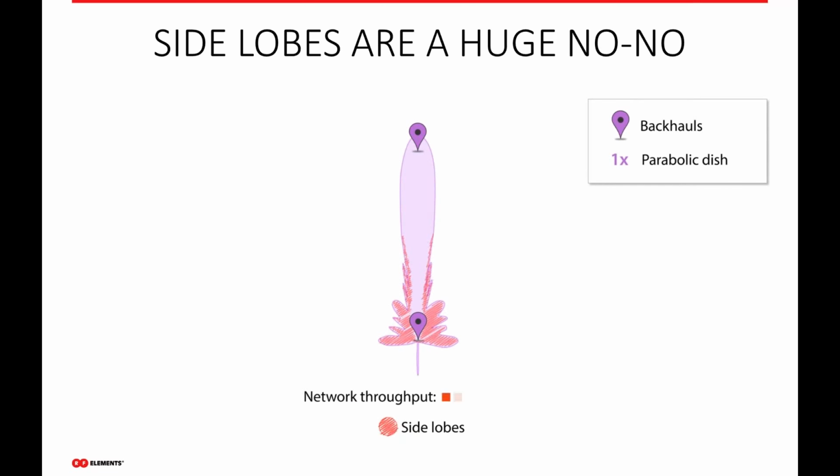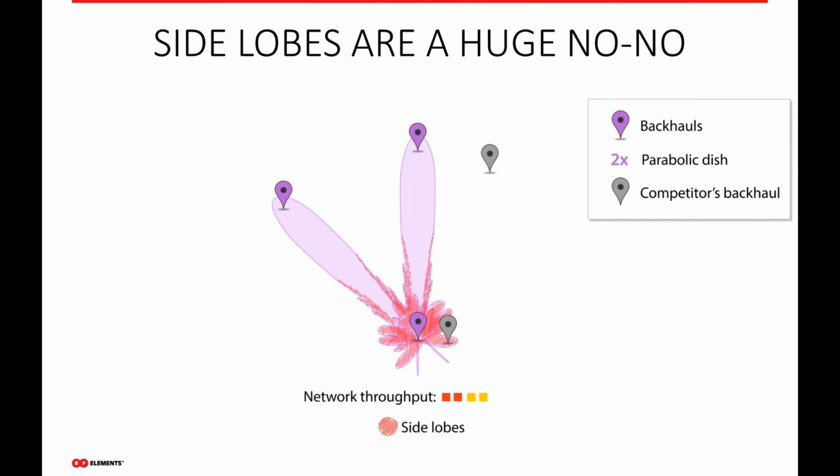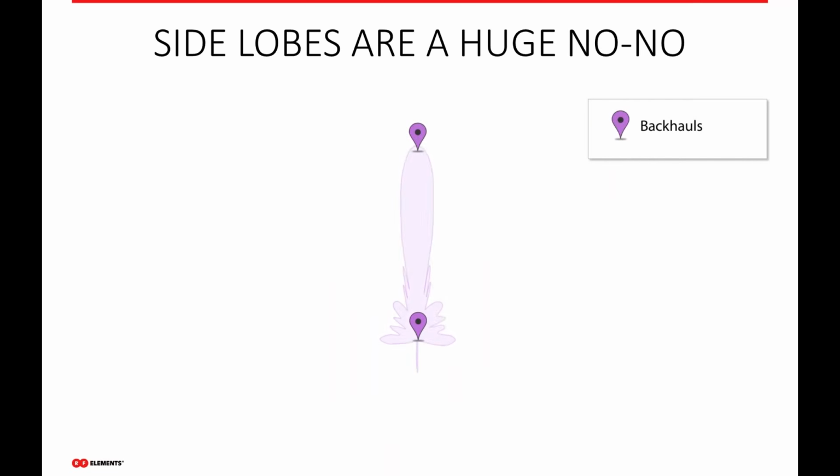Maybe it's on a guy leg where you have these big distances. Again, these side lobes are capable of interacting, hearing, and talking to each other, and really start causing issues and reducing your overall backhaul throughput, which is again a huge problem, because without your backhaul, you're not getting that bandwidth that you need to your tower sites to again deliver all this bandwidth that's required of your customers.